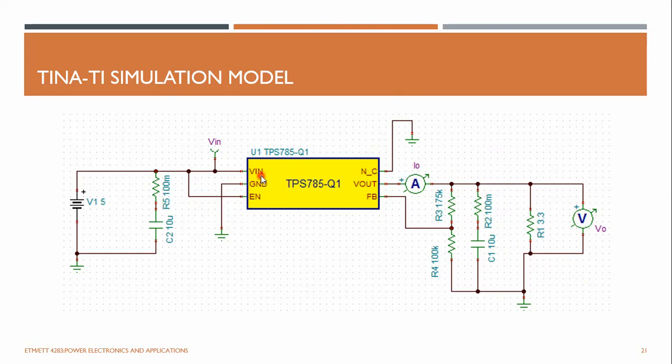That means the output is disabled, and only the standby quiescent current flows, so that will save the battery life of the supply. So if the user gets the phone in his hand and turns on the device display, then the control circuit detects it and enables the regulator that will provide the power to your display.